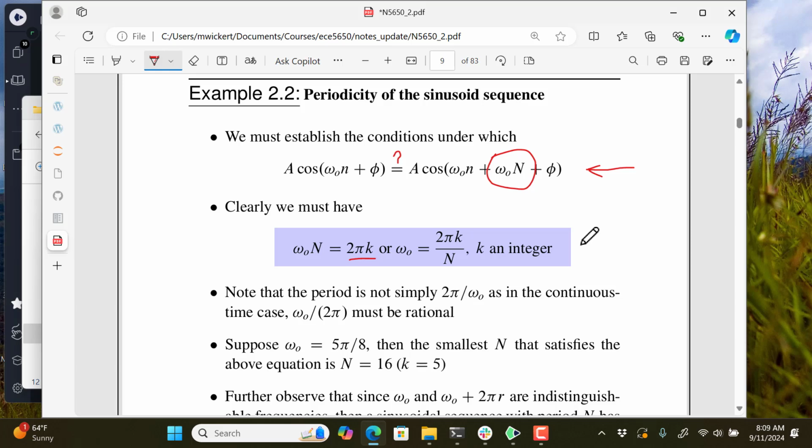I think maybe it's 64, and then it just keeps playing those same samples over and over again as the interrupt service routine fires in the real-time part of the loop. It just keeps pulling another value out, pushing that out to the digital to analog converter, and when it gets to the end, the table wraps around with a modulo and it starts all over again. But if that's not the case, then you don't always have that situation.